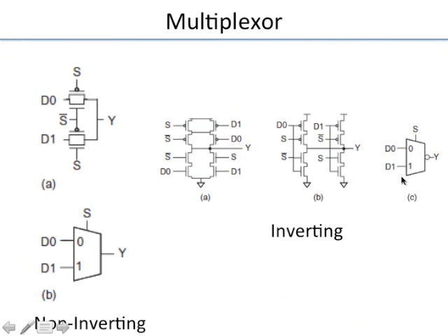And see, this is an inverting multiplexer, right? Because it's built like this, it's an inverting multiplexer. There is a bubble here, whereas this is a non-inverting multiplexer. So once you can build a NAND gate, a NOR gate, or a multiplexer, even if you can build just one of these three, each of these by itself is what is called a universal gate. You can build all Boolean functions using these gates. So any complicated Boolean function you can build using cascades of these gates with appropriate inputs to these gates.